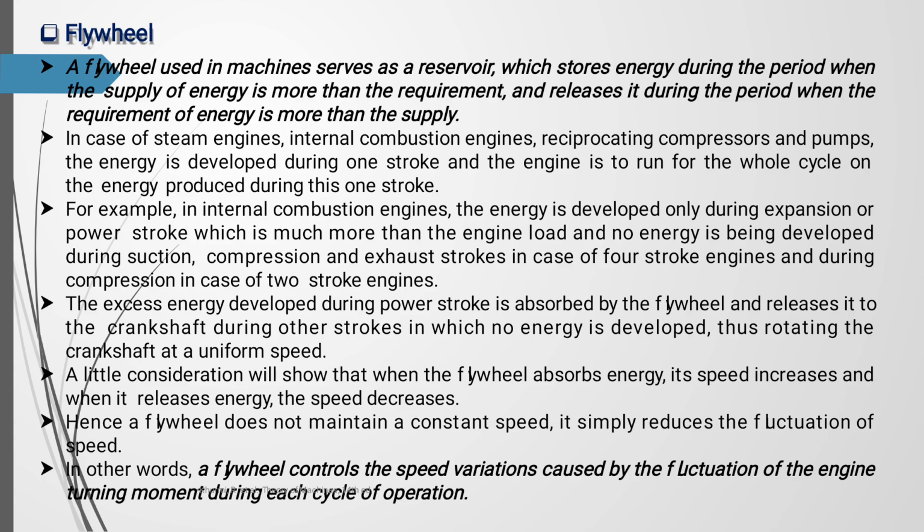A few slides before, I told this. The energy is developed only during the expansion or power stroke, which is much more than the engine load. So the energy can be absorbed from that and stored in the form of kinetic energy, and no energy is being developed otherwise.